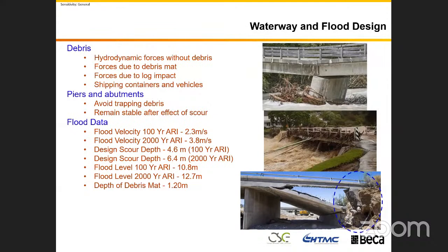So there is absolutely no point designing a bridge above the flood level at the road, because all the roads will be flooded. So no point in having a bridge above the flood level, right? So that was the answer given to me. Similarly, when I was in Sri Lanka, I knew that in Colombo, at the spillway, there is a bridge over that spill tail canal. When there is a flood, that bridge always gets washed off, and people told me at that time they knew it was going to be underwater. So that's how the design was.